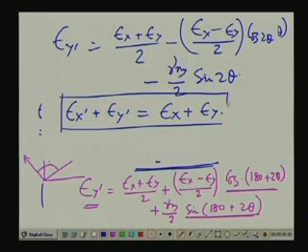If you remember, when we evaluated the stresses at a point with reference to different orientations of axes, we had seen that the total stress values remain constant: sigma x plus sigma y is equal to sigma x dash plus sigma y dash. The same thing holds good for the strain as well. The strain with reference to the rectangular axis system, epsilon x plus epsilon y, is equal to epsilon x dashed plus epsilon y dashed, with reference to the x dashed and y dashed axes.